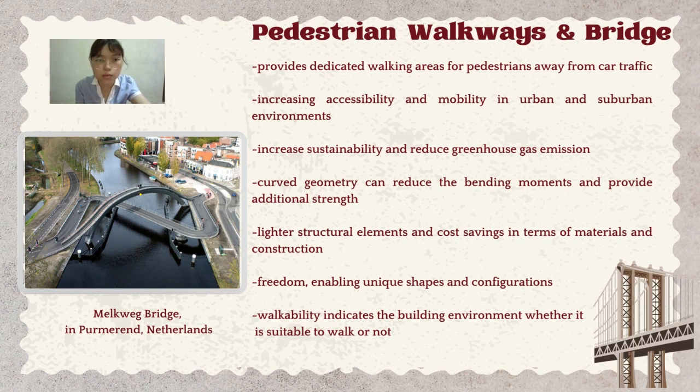The curved beam was used in a wide range of civil structures, such as to construct the pedestrian walkway because the curved geometry can reduce the bending moments and provide additional strength to make the bridge supply more efficient load transfer than their straight or flat counterpart. This can result in lighter structural element and cost saving in terms of material and construction. The curved beam also provides design freedom, enabling unique shapes and configuration to satisfy the specific project needs, and also to create original and innovative design that fit the site environment.